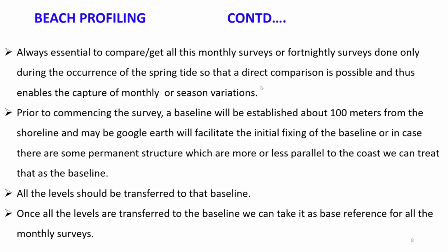Although fortnight surveys also would help, but monthly surveys should be good enough, and it is done only during the occurrence of spring tide, so that a direct comparison is possible and thus enables the capture of monthly or seasonal variations.